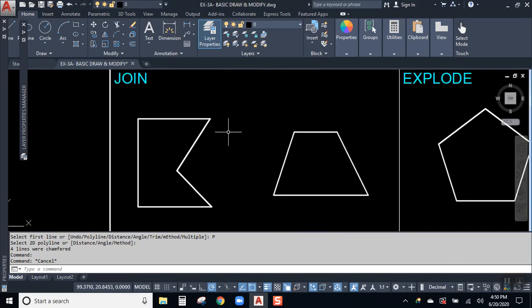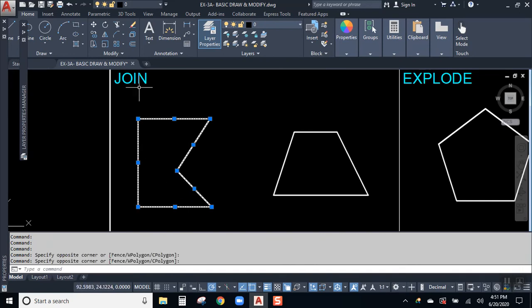Now, we've talked a lot about lines and polylines, and I see here that I have lines. And, you know, sometimes we're going to say, I wish I had made this out of polylines, and you might be tempted to just trace over it using object snaps to recreate geometry on polyline, but you don't have to do that, because we can take line segments like these and then join them together into a single polyline.